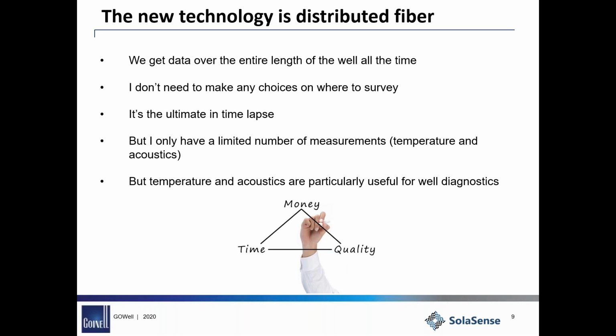And again, for cementing purposes, my personal preference, I kind of like the cement mapping tools, where you get some sort of circumferential view of cement, so I know, yes, it's there, and there are no obvious channels in it, and it's bonded to at least the casing, if not the formation itself. So I'm always a little bit cautious when we talk about cement, and that includes cement logs, because they're great for telling me about the presence and quality of cement, but nothing about hydraulic isolation.